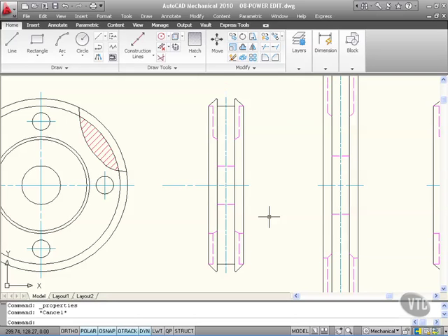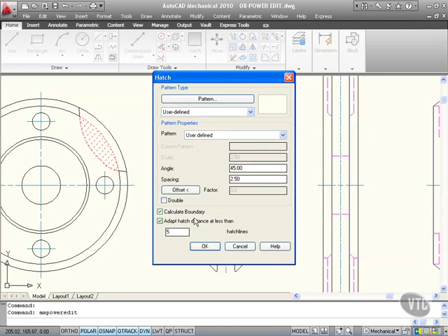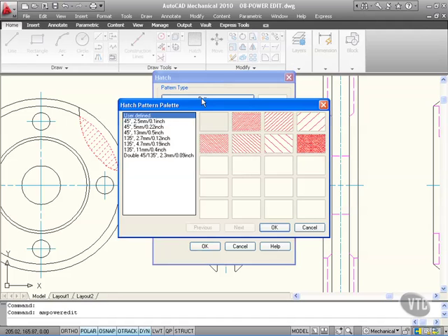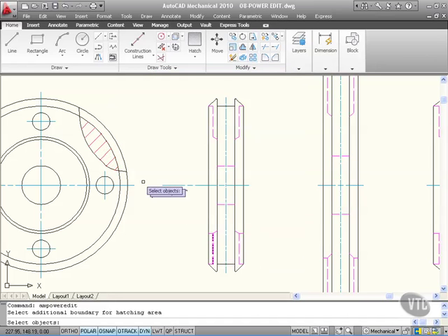It's just a double click. That's all it takes. If I double click here on this hatch, as you can see, it is a hatch pattern, and I can go in and I can edit that hatch. That is an AutoCAD Mechanical object. It's an intelligent object, so I can change the pattern if I want to. I can change it to, say, that pattern there, a double cross hatch. And as you can see, I OK that and I OK that. It changes in size, so it doesn't really show very well.